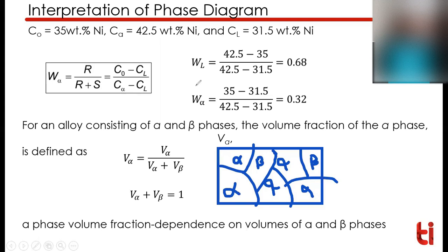Now what you do is measure this rectangle area, this length and this length. This is a 2D way basically, 3D is difficult, so it will give me area fraction, not the volume fraction. Roughly, if you know the thickness, you multiply by the area, then you have a volume fraction also, no problem.